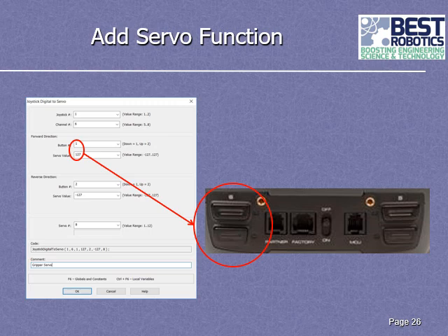So a servo has a center position when it's at rest at the 0 mark, and then you can go plus 127 or minus 127. In this case, we're going to go plus 127, which says go as far to the right or open as you can go. Now, once you put this into place and you decide, I don't know if this is exactly how far I want this thing to open, you can come back in here and play with this number until you get it to move exactly how much you want.